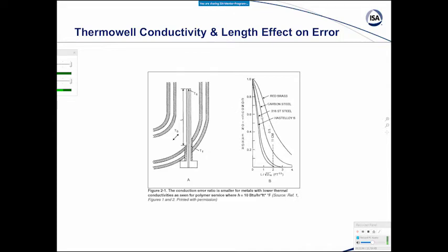And we see that for metals, like stainless steel and cast alloys, they're pretty much similar. You get into carbon steel, which is kind of unusual. I guess brass could be for water streams, not that unusual, but you get into problems. Not shown here is when you have protection tubes that have low thermal conductivity, then boy, you really got a problem, and that's why I really don't like to see ceramic protection tubes. Hopefully there's some alternative to that because of the low thermal conductivity of the ceramic.